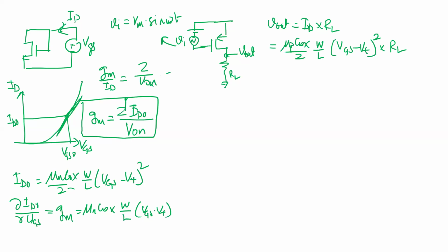So I'm giving an audio signal on top of some bias voltage VGS0. So that VGS0 makes sure that you have some bias voltage, and then on top of that, I'm giving this tiny audio signal to amplify it to this amount here. Okay. So I'm going to substitute VGS to be VGS0 plus Vm sine omega t and expand that and see what happens.